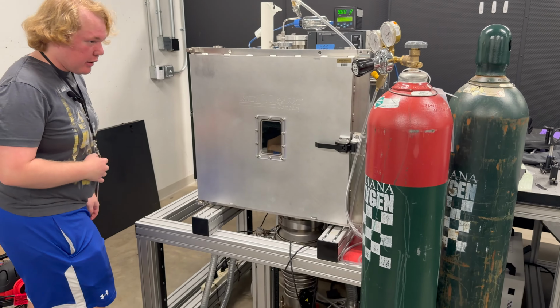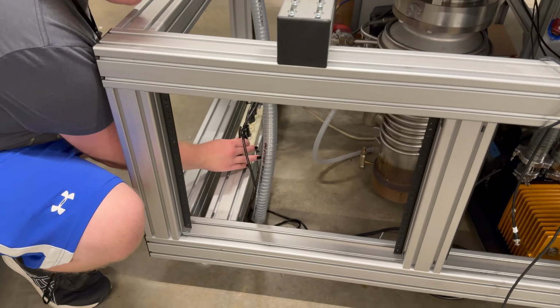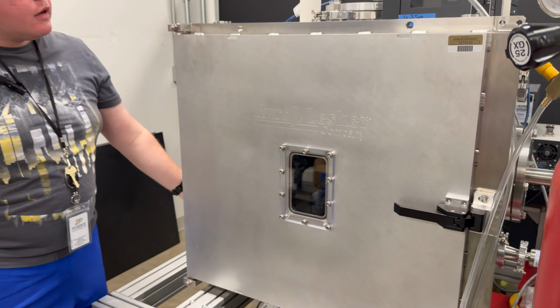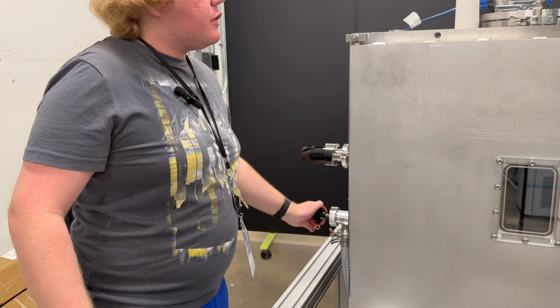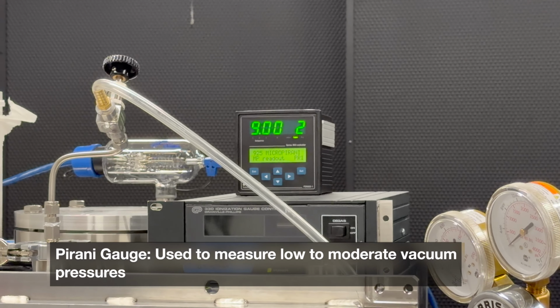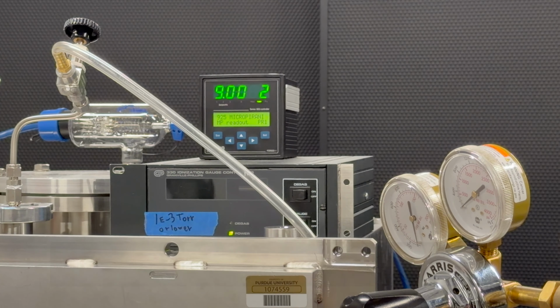The first step is to plug in our roughing pump. And then we'll let that run for a couple of seconds, and then open our chamber to the pump so that it can start lowering our pressure, which we will see start to drop on this Pirani gauge. It sometimes takes a couple minutes.